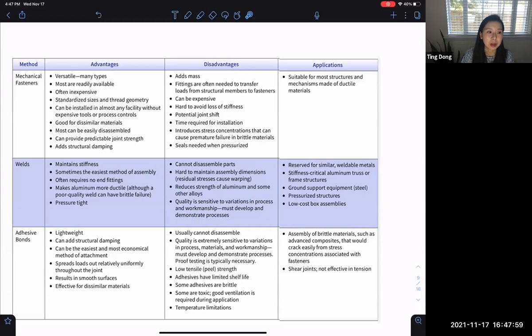And a benefit of using fasteners is that it's much easier to repair if there's some damage. With a fastener, you can easily remove it and attach a new one. But with welding, you need to put your vehicle at a specific location and use specific equipment. The repair is not as convenient as with the fastener.